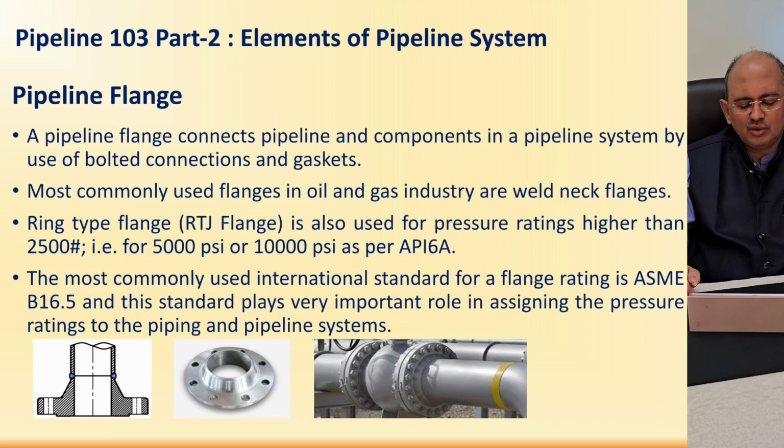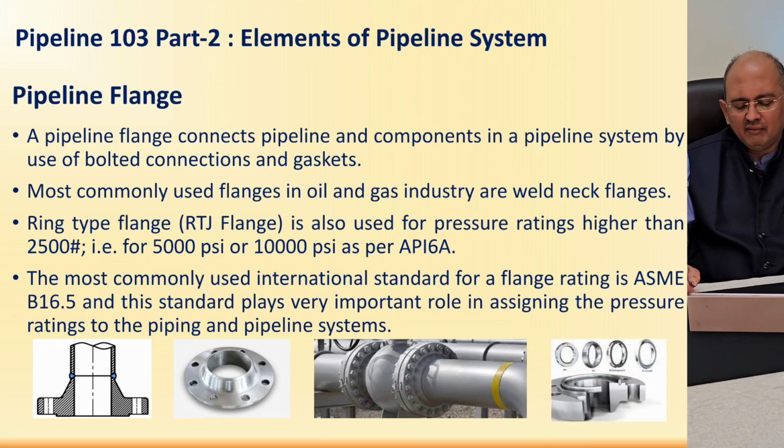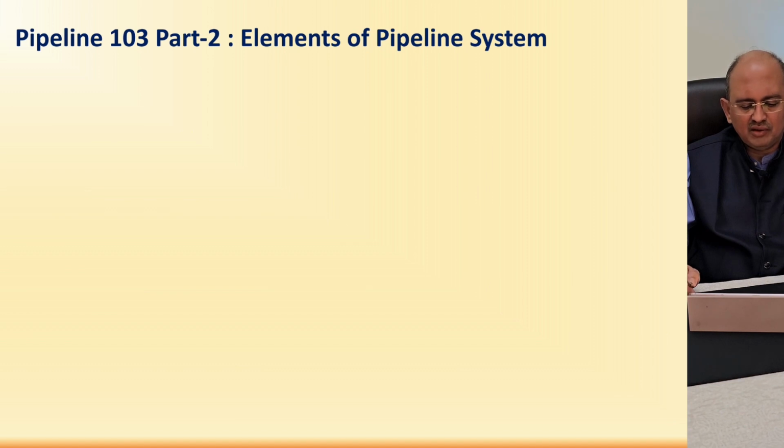This is one example where the flanges are welded to the pipe, and then in between such two flanges, the valve is connected. So basically, this is a flanged valve which can be removed and inserted or replaced whenever required. So that is the advantage of having a flange joint. And this is a typical ring type joint shown, which is for high pressure. So you can see a groove in which a loose ring is inserted, and it is basically used for the very high pressure applications.